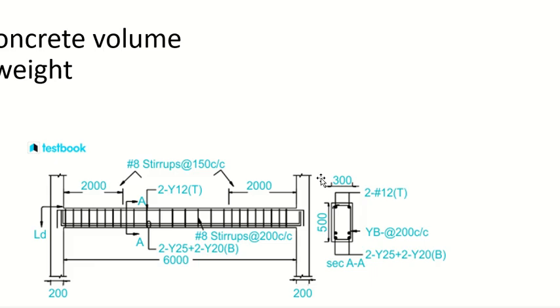If I try to bend this thing, the bend length will be something significant, right? I cannot ignore it. If something thin is bent, the bending length is not so much. But if I bend something thick, the bending length will be something which I should not ignore. So this bend length is considered as 2 times of dia. This bend is 2 times of dia, and this thing which is straight is 6 times of dia. So total 8 times of dia.